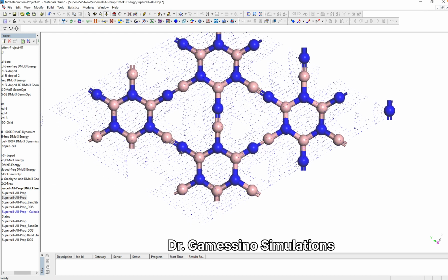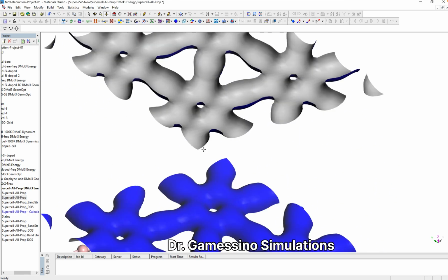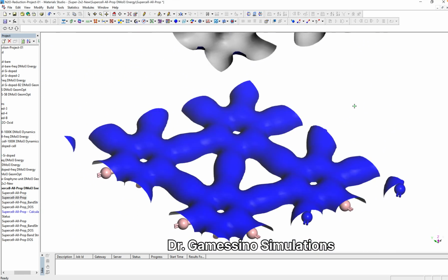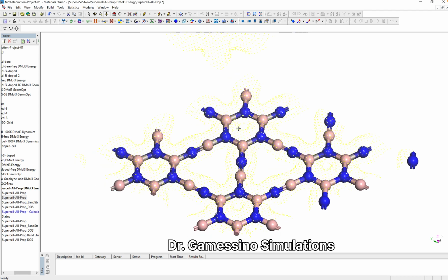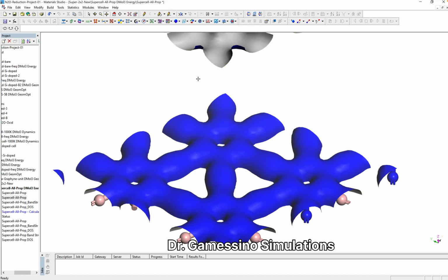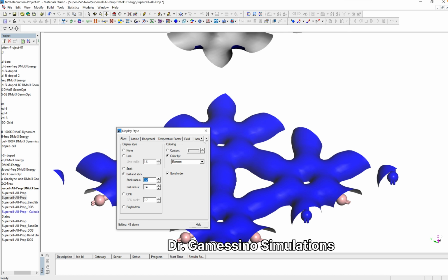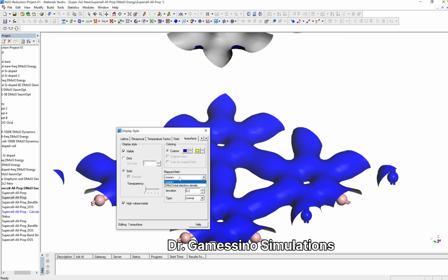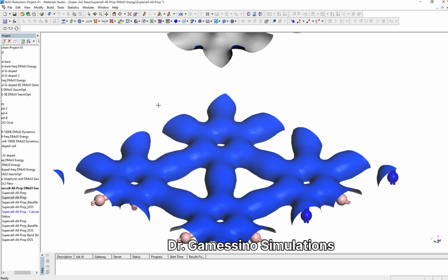This will show you the electron density plot. So now we will convert this to a molecular electrostatic potential map. So right click on this view, go to display style, and then select the isosurface and select here total electron density, and the value will be 0.2. So this structure is not showing us which site is electronegative and which site is more electropositive.